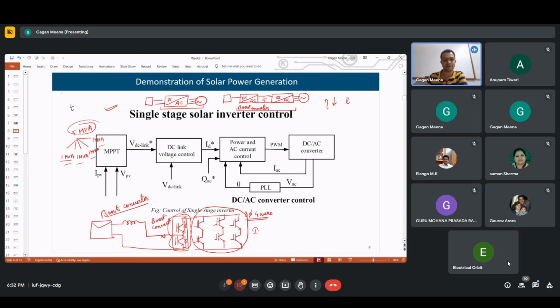Those give analog output, we convert it into the digital domain, and the DSP works in the digital domain. OpenRT has both digital input and digital output. Since these switching pulses are digital, we can directly provide D1, D2, D3 to OpenRT's digital input, and then monitor all these things on the CRO or DSO, the digital signal oscilloscope. So we can validate whether our control logic is working or not.